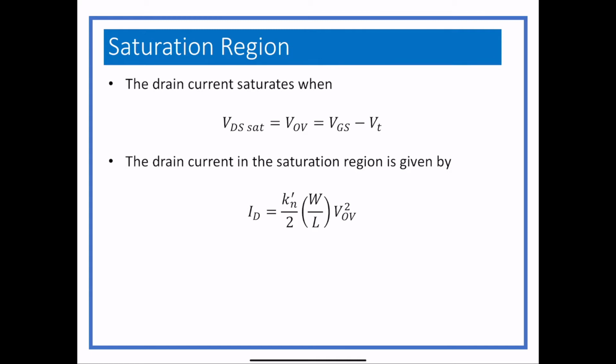Width over length, we've talked about where the width and the length is in a MOSFET. The width is going back into the page. The length is the distance between the two heavily doped channels. And the more standard way of representing, sometimes we use VOV for simplicity's sake. Say if we're trying to find that value or find VGS, we might use the overdrive voltage to solve and then go ahead and add on the threshold voltage in order to get that value.